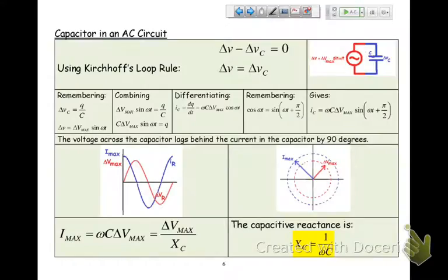So then when I do the same kind of analysis for my capacitor, again, I find this graph looks rather like the previous graph, but if I take a situation like this, there's my time interval, then I see that my voltage has only gone around there a bit, whereas my current's gone around there a lot more. And I see it much easier in this phasor diagram than I do in this graph. So phasor diagrams are very useful. I know it's something new, but nothing's added just to fill up space. Everything is added because it earns its keep. And phasor diagrams can really help you out.